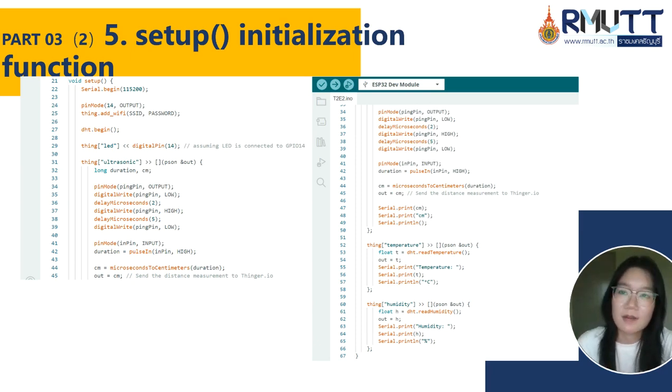And this is part 5, the setup initialization function. It completes system initialization, including serial port configuration, pin mode settings, network connection, and the cloud service loading. This function is executed only once when the device is powered on or reset.